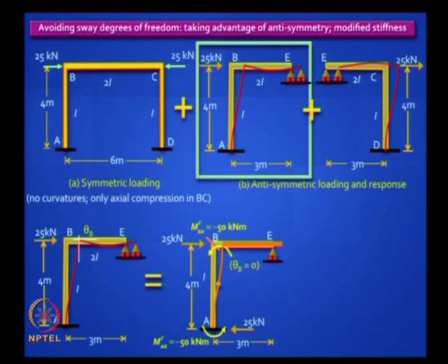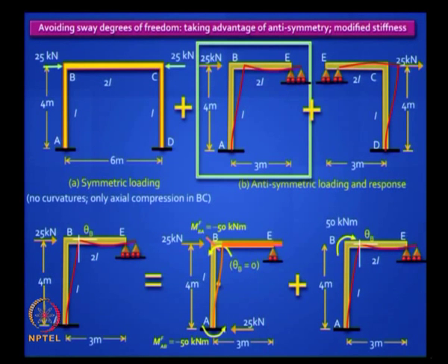So you know everything. You've got the fixed end moments. Now what should you do in the displacement method? You have to release that moment which accumulated at the location where you artificially fixed it. So the correct answer is this plus that. Now that second figure is something we have analyzed earlier. Remember, it is a single unknown problem, concentrated moment, nothing to worry.